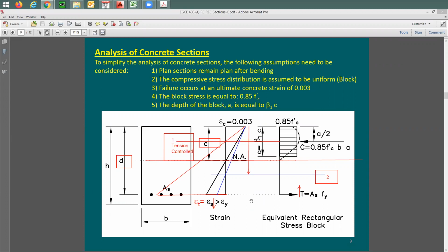Also, material properties. Let's say I didn't give you the concrete strength, what would you do? You just look at some of these examples. Usually your backup information is going to be all of these slides. So you just go back and pick some reasonable value. You don't go 6,000 or 7,000 concrete, but maybe 4,000, 4,500, 3,000, some value there. If the steel is not specified, you use grade 60, which is 60 ksi yield strength. So if I didn't mention it, don't say I have misinformation. No, it is not missing, but you need to come up with your estimate.